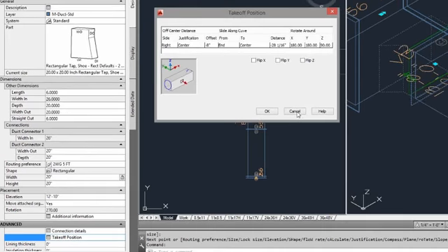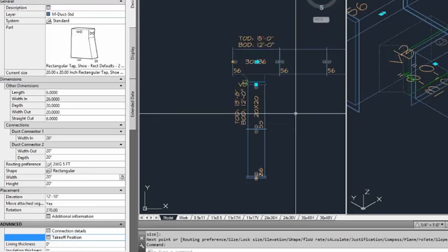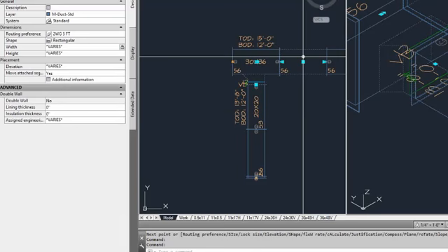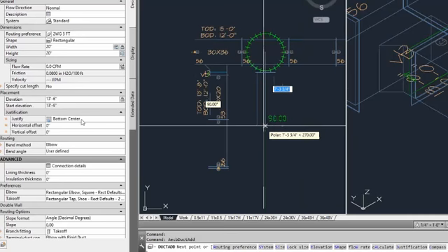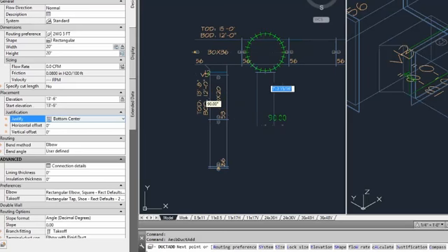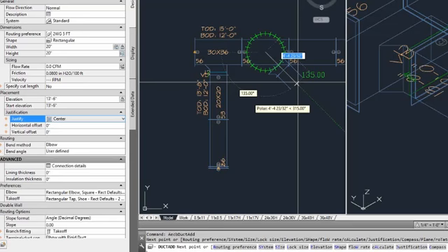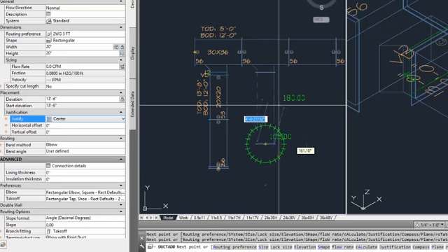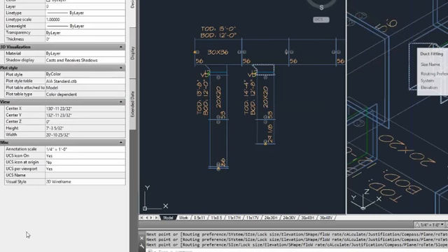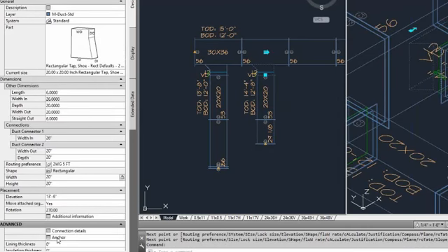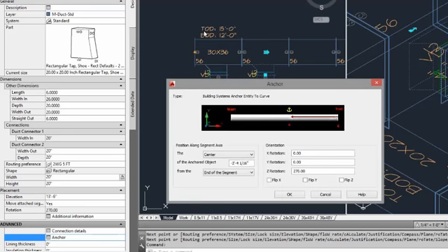Now if you notice what I said earlier, I said that when you pull with the plus grip it doesn't place the correct anchor on there. I just needed to clarify that just a little bit. When you have a center justification and you automatically pull the tap out of there, you can see it was placed in the center of the duct. When I select that and I come down here again to the property palette, you can see now that there's something different there. It says anchor. And when I select that, it gives us a totally different dialog.